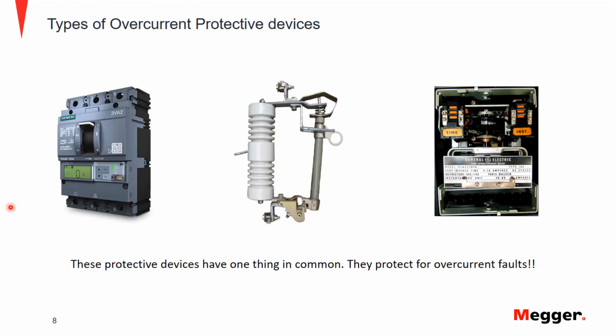And then the third thing we have is the electromechanical relay. What this guy does is he actually senses fault conditions by using CTs, or current transformers, that are either coming from a breaker transformer or even some external CTs that are in the yard. So when the predefined setting of the overcurrent relay is exceeded by the tap value, the disk will move and close a set of contacts which attach to the circuit breaker trip circuit, and therefore it will open the associated breaker that's tied to the trip contacts of the electromechanical relay.